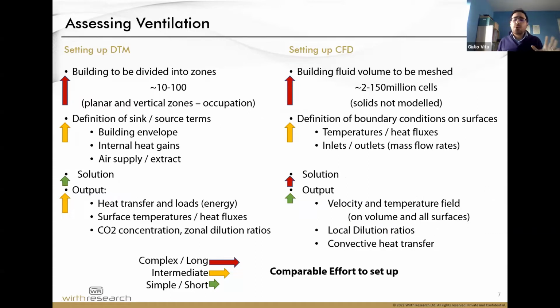So how complex is it to set up a DTM simulation compared to a CFD simulation? Our opinion is that there is a comparable effort in setting those up. The complexity of the DTM comes from the huge number of parameters that you have to input in your simulations. Those parameters are a bit fewer in the CFD. The CFD is still complex though, because you need to discretize your model and divide it into cells so that you describe the flow features correctly.